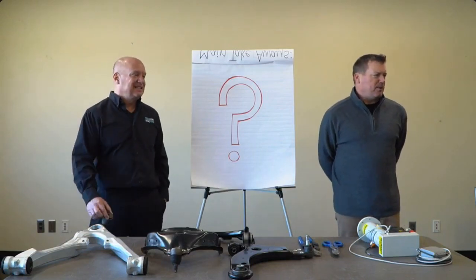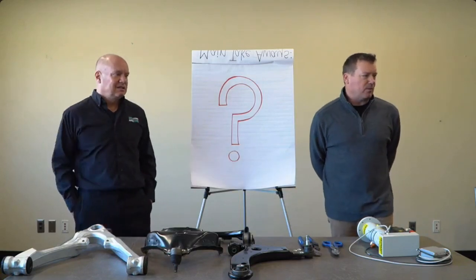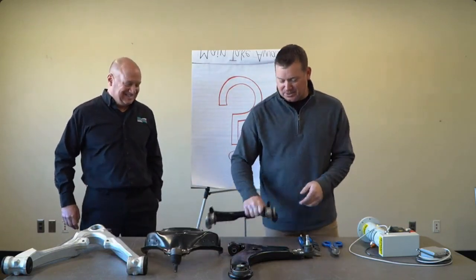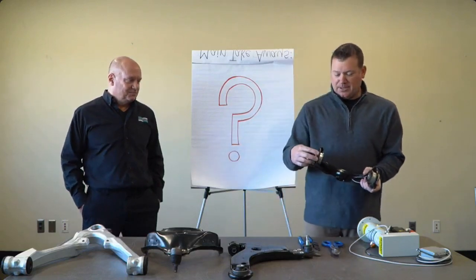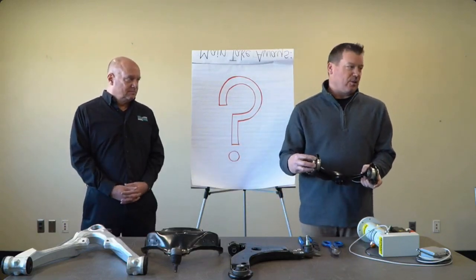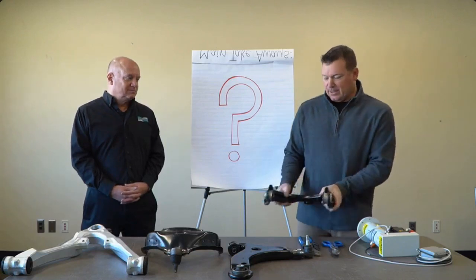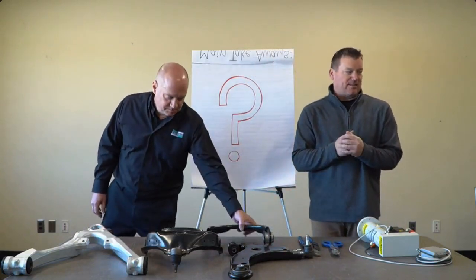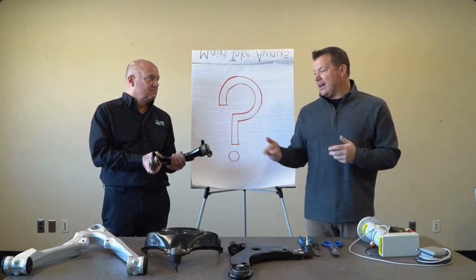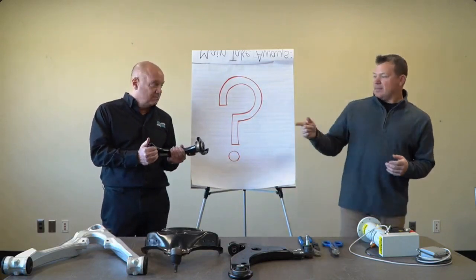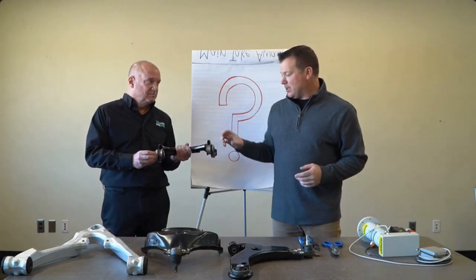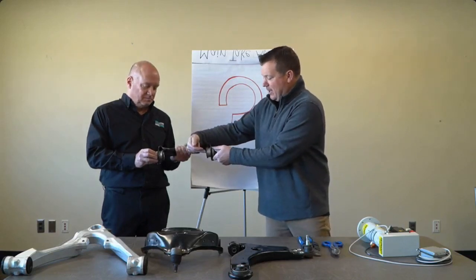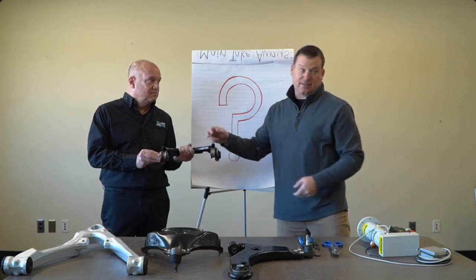Sorry I came in late, and maybe you covered this, but how do you account for the flex in the part while pressing the bushing in? Well, I just mentioned that. When we're pressing the bushing in, our measurements are taken when it's not under load, when there's no force on it. Our measure step or measure command we talked about earlier has that built into it. Other mechanical components help too: maintaining contact with the probe using the spring-loaded detail on the end of the press allows us to back off and still maintain contact with the probe. That takes the deflection out of the equation.